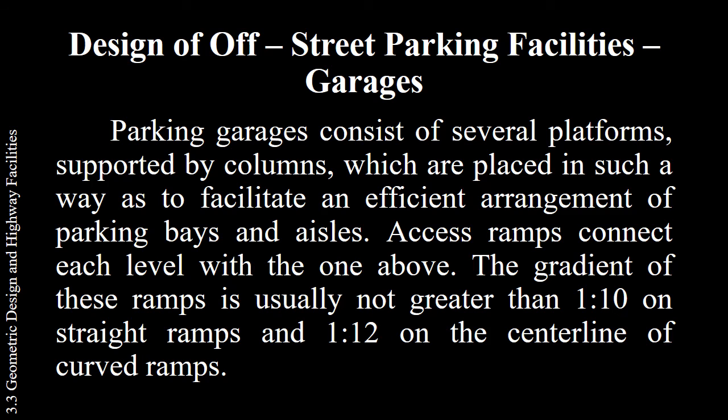Design of off-street parking facilities for a garage. Parking garages consist of several platforms supported by columns which are placed in such a way as to facilitate an efficient arrangement of parking bays and aisles. Access ramps connect each level with the one above. The gradient of this ramp is usually not greater than 1:10 on straight ramps and 1:12 on the center line of curved ramps.